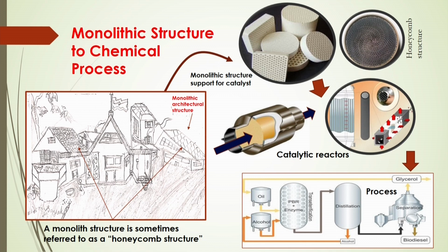The reactor based on the monolithic structure is one type where the chemical engineering process can be intensified based on the contact between the phases, the retention time and other hydrodynamic aspects, where we can get the benefit of flow characteristics, flow patterns, even mixing characteristics, ideal flow or non-ideal flow, or plug flow, based on this special structure of the reactor internals.